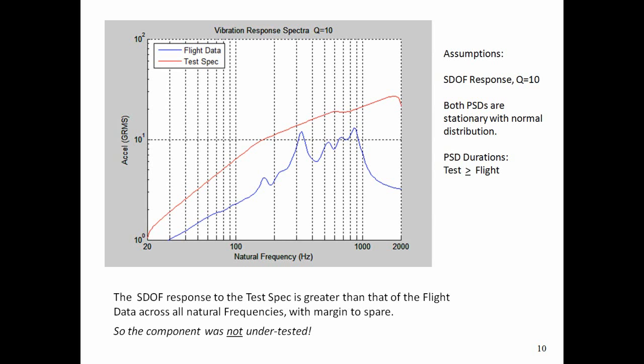Well, in order to resolve that question, we can turn to the vibration response spectrum tool. And hopefully we can show that our original test spec envelops our new test specs in terms of their corresponding response spectra. In that case, retesting is not necessary. Now, program managers never ever want to retest a component because that costs money, it costs time, it costs potential schedule slip.